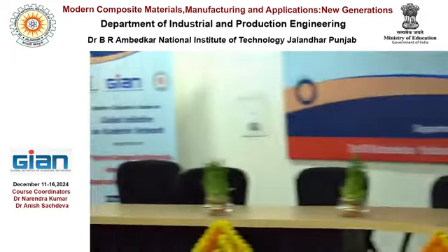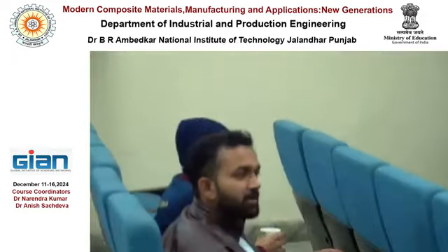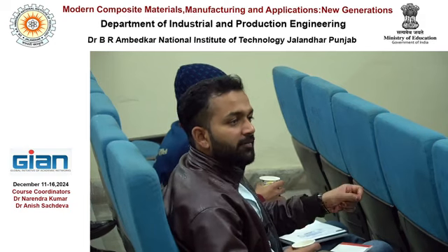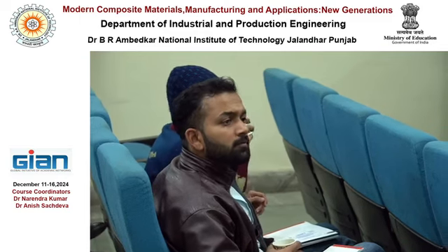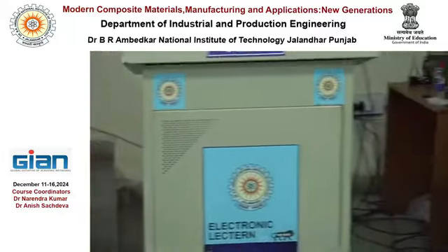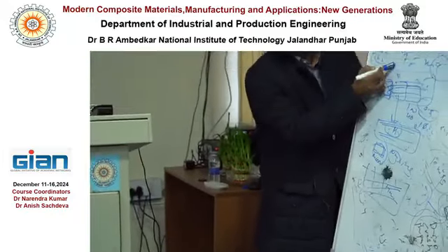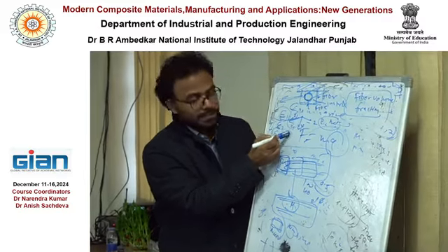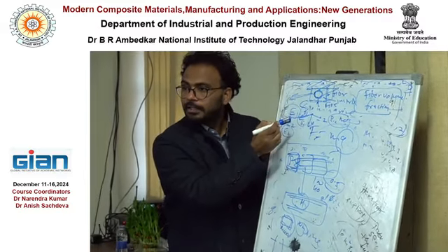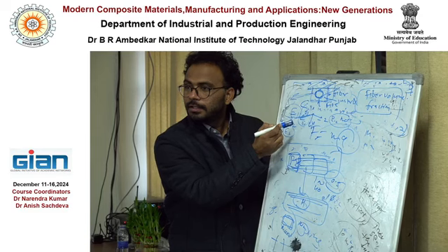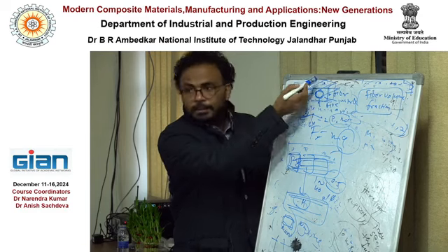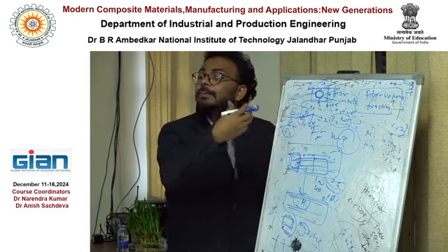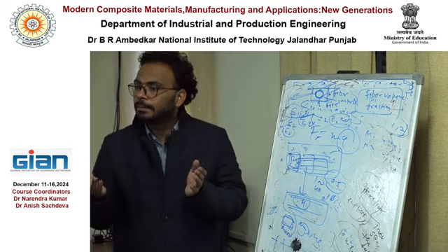So what we are doing, we are laying up the plastic firstly, 4 layers, and then laying up the fibers. Then you can choose the lamina RVE. When you create the RVE, suppose you create 1 mm by 1 mm. This one, plastic. On top of that, plastic, and then multiple layers of plastic, and then fiber, 1 or 2 layers, and then again plastic. So then you can create the layered RVE accordingly. So lamina RVE is a different way. You can read about the creation of lamina RVE on Google.